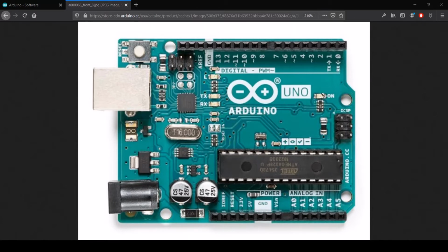So this on LED, I'm guessing you guys already know what this will be. If the Arduino is connected, this will be green. So it means the Arduino's on, it's working, it has power. The transmit will be if the Arduino is sending you any data. So if the Arduino is sending, for example, via Wi-Fi, Bluetooth, or even just to your computer, some print statements, the transmit will be flashing. And then the RX means receive. So this is if the Arduino is receiving any data. So for example, if you have any sensors hooked up, like the distance measurements or temperature measurements, any type of sensor or any reading, this light will be flashing.